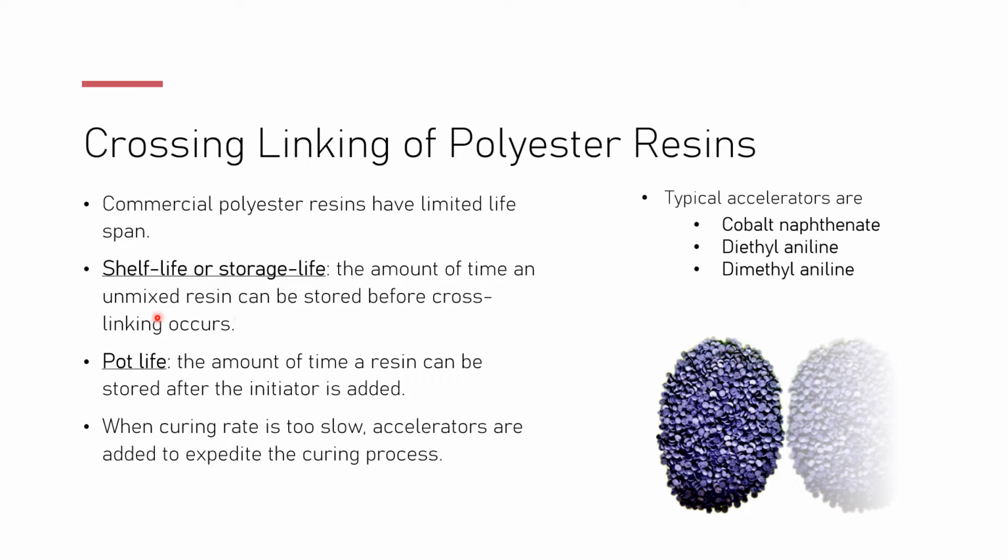So it definitely has a shelf life or storage life, the time that this resin can be good, because it can go bad. Therefore, you have to find the amount of time for each type of resin. Even though we're studying the thermoset, you still have different kinds of thermoset plastic. So it depends on the type of resin; the shelf life or storage life varies.